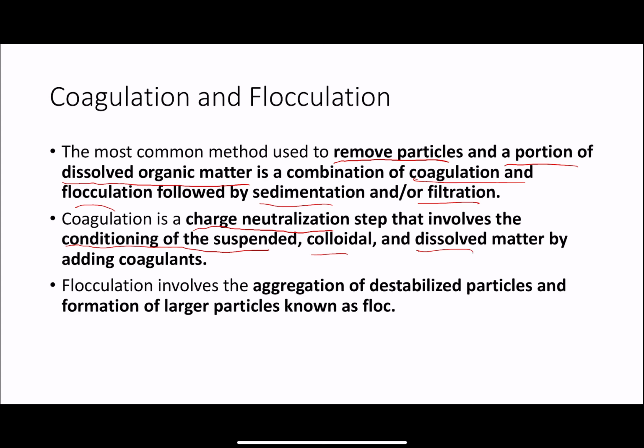Flocculation: once you neutralize all these particles, now we need to do aggregation of destabilized particles, and of course, formation of large particles, which we call floc. So these particles will aggregate and then make larger particles.